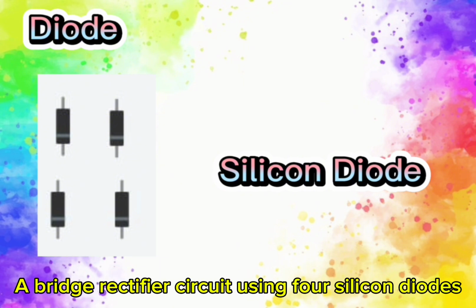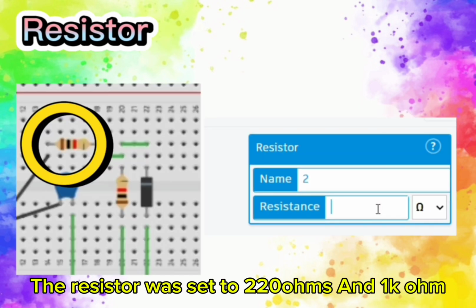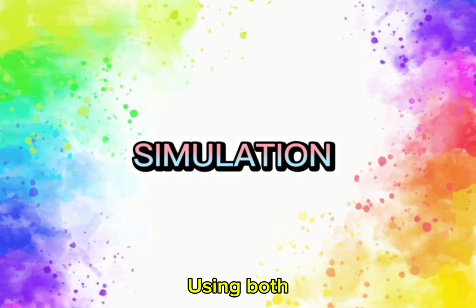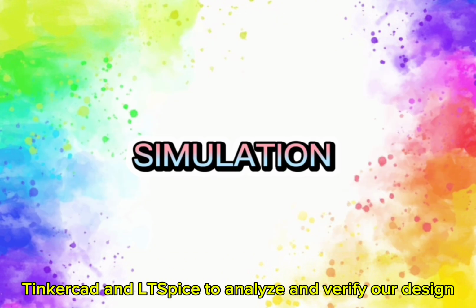A bridge rectifier circuit using 4 silicon diodes. The capacitor value was set to 1000 microfarads. The resistors were set to 220 ohms and 1 kilo ohm, and then the Zener diode was set to 5.1 volts.